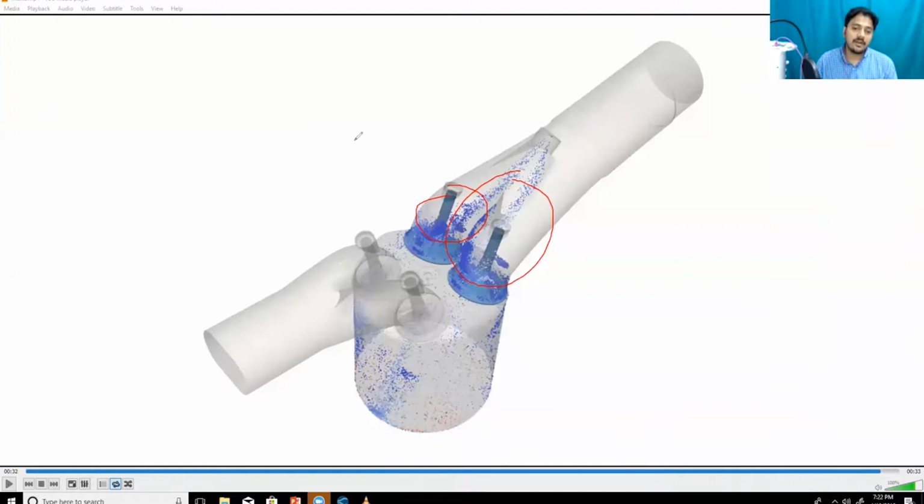So basically, out of your injected fuel, say that you are having 100% fuel. Let us say 5% is trapped inside your port, only 95% comes in. This is during your first cycle. But then during your second cycle, this 5% will first come in. So inside your engine, you will always have 100%, and you will always have 5% in the port. So the system kind of reaches an equilibrium at that point.